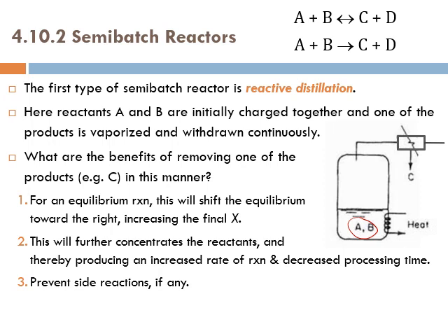So if C was very reactive in such a way that it could react with D to form another product, or react with A or B to form other unwanted products, therefore here, if possible, it's better to remove C. So these are the benefits of using reactive distillation, not to mention that you're also getting almost pure C.